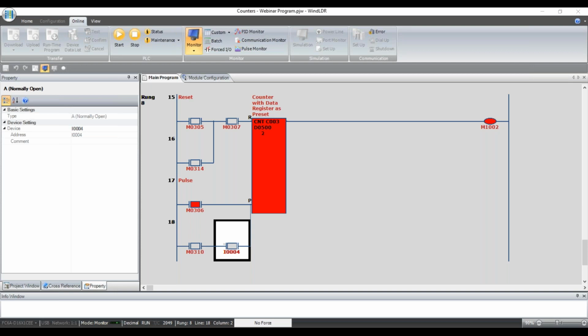Let's see, what other questions do we have? For example, let's say I have 100 pulses per gallon. I count for an hour. I want to immediately start the counter without losing any input counts. If you want to make sure you don't lose any input counts, it depends on how many gallons you're planning on getting per hour. If it's 1 gallon an hour, then the standard counter will handle that. If you're doing 5,000 gallons an hour, then you'd want to definitely go with a high-speed counter and use the high-speed counter controls to do that.